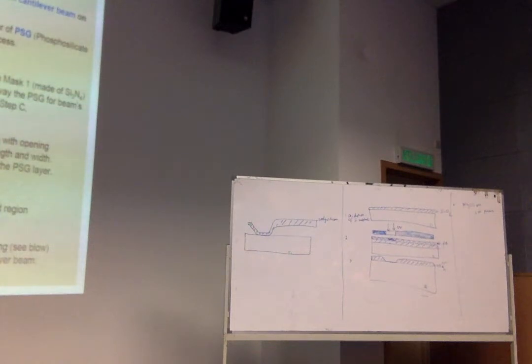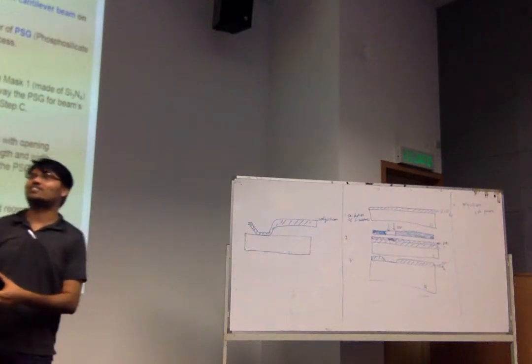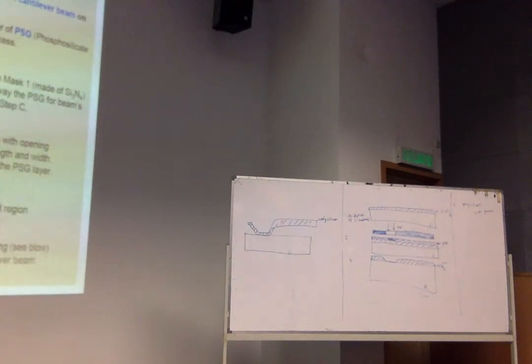So if you see here, the wafer is not wasted. Rather, some lithography steps and some deposition steps were used to achieve the cantilever beam. This we call the surface micromachining process. Now it is so easy to draw some drawings and say it in some steps, but it's quite tedious to do. Even in the lab we are just doing a single layer mask. That means we just keep the mask, expose it, and don't worry about the next layers. But this involves at least 2 mask layers, so there is an alignment between these.